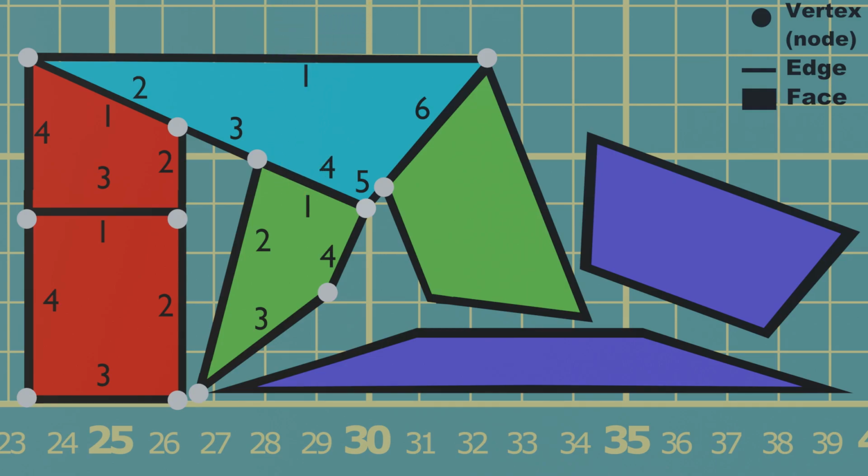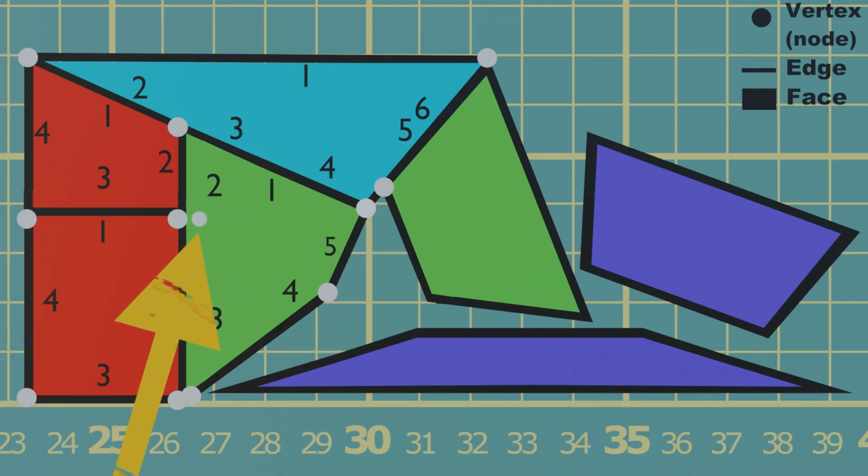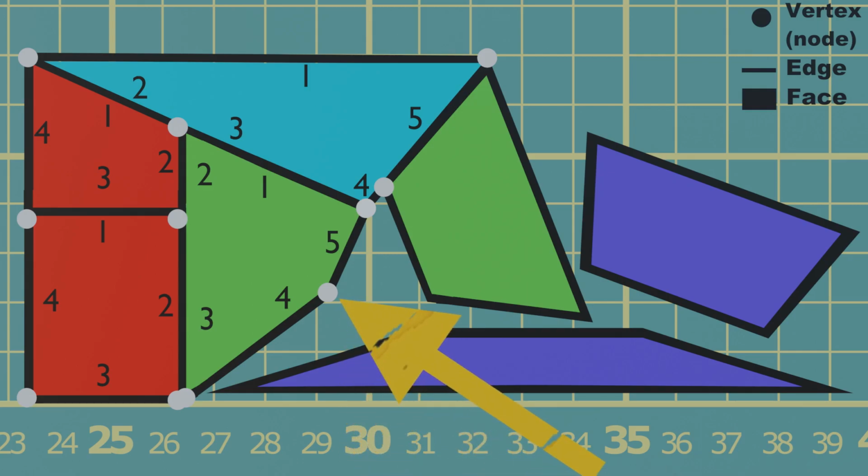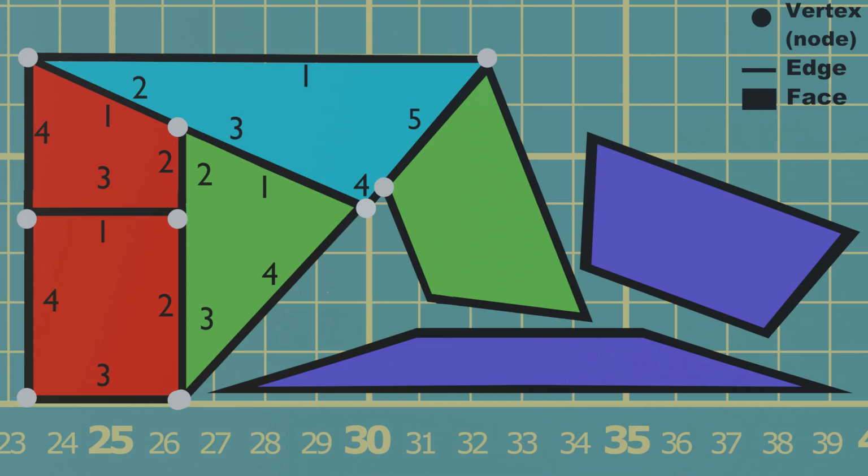Now take a look at the green shape next to the red one. We start with 4 edges and we want to connect to the top vertex, the red and the blue one. But to connect to the red shape, I need to create another vertex, basically creating an n-gon, ending up with 5 edges now. Here I can easily solve this by straightening the edges 4 and 5, or eliminating the vertex here, and I have a quad again. Notice how the big n-gon on the top also loses an edge. We have 5 now instead of 6 edges, so we're making good progress.